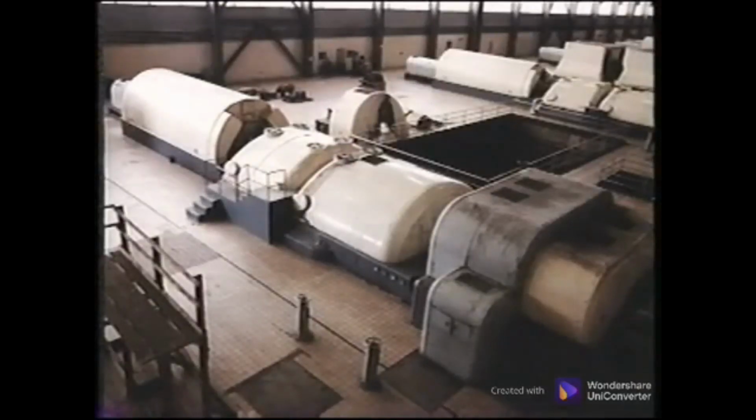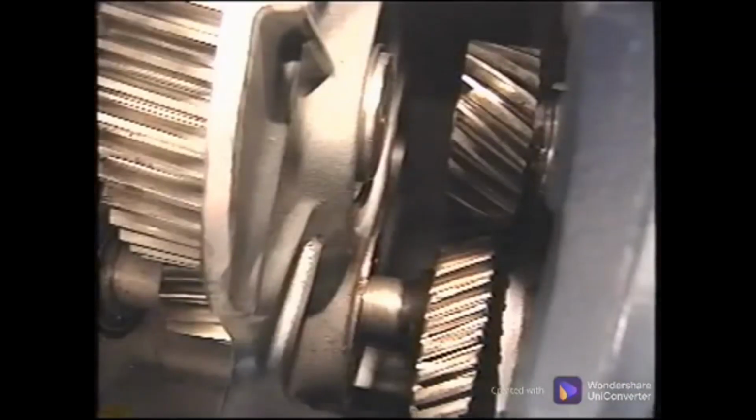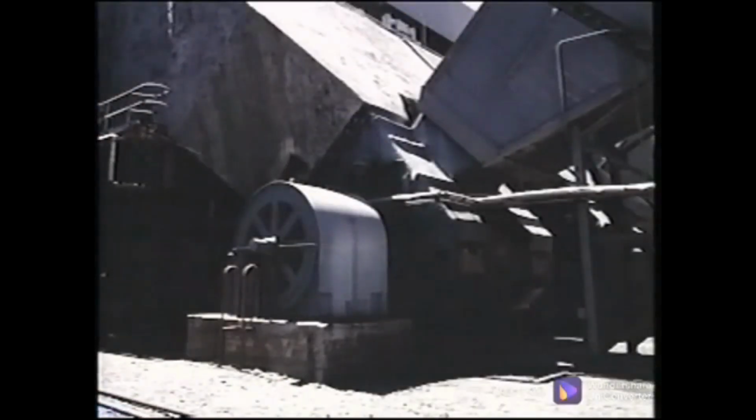High-speed machinery must use a low viscosity or lightweight oil, while the lube of slow-speed machinery should be higher viscosity or heavier. Since the lube should provide a film between internal components, heavier loads such as gearboxes require a heavier oil. Light loads require a light oil, and if a heavy oil is used, extra energy is required to move the components, producing heat and degrading the oil.